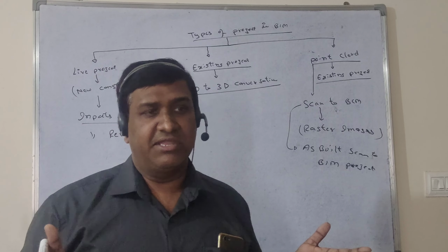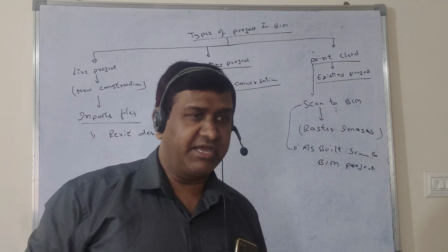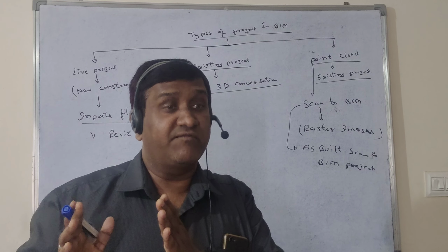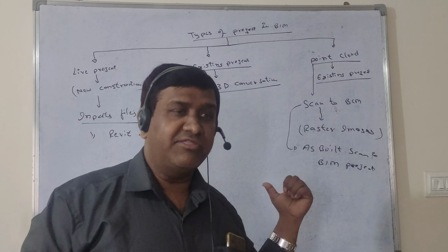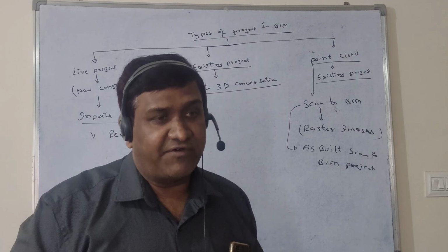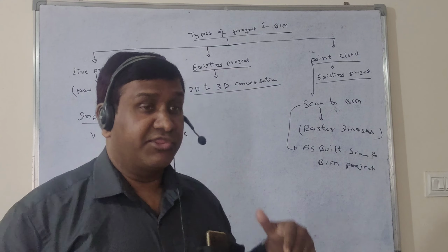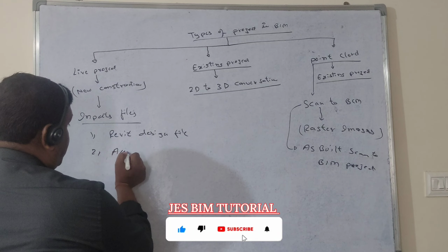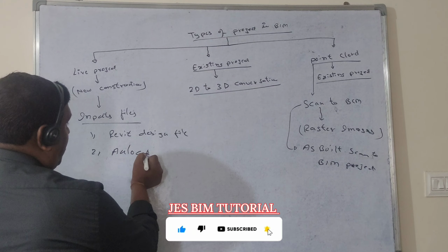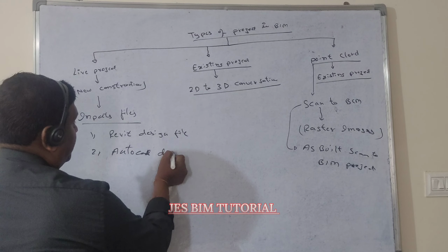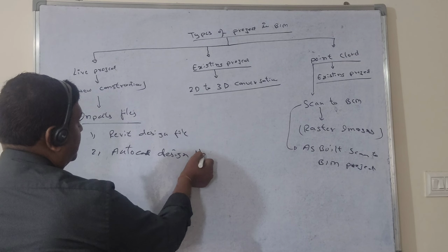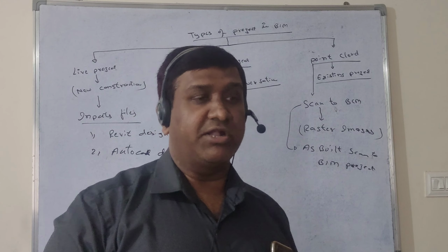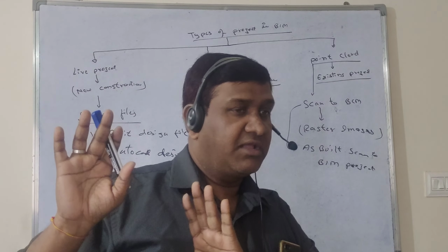Do you know tender drawing? When people are going to take a tender for a new company project, they prepare some drawing, which we call a tender drawing. Like that, the design file will also have some tender information, like overview information. So you will get this REVIT file, and some companies may also give an AutoCAD design file, because the design has already been done, but we have to create that design into a BIM model with full information.